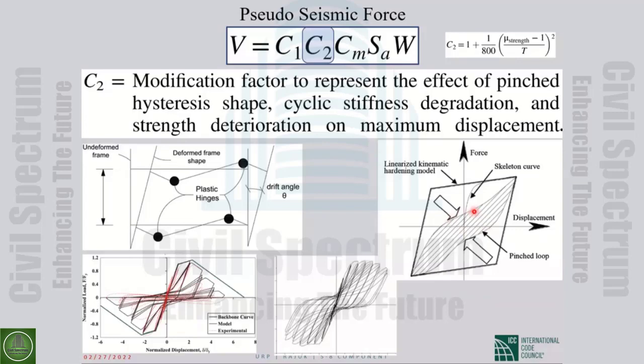For example, when a beam in bending gets lots of cracks, and we want to impose a bending moment on it, first the cracks should close, then the stiffness increases. So there is a distance that it moves without that much force. So it doesn't dissipate energy.